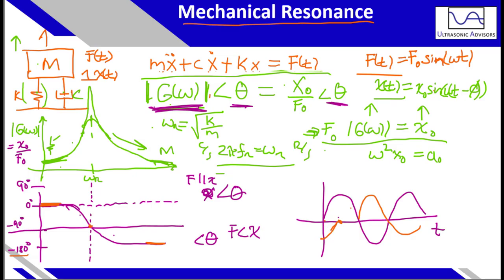In order to better understand force transfer and energy transfer, because of the power input into the system, it's better to look at velocity. So velocity is out of phase, is ahead. So if we had, at lower frequency, displacement here, velocity would then be lagging displacement by negative 90 degrees.